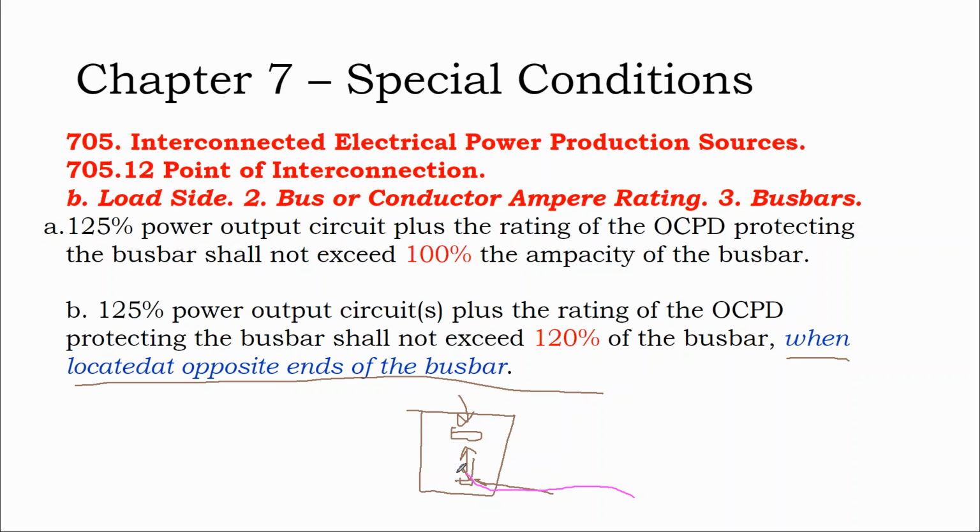So the bottom source feeds the bottom loads, and the top source feeds the top loads, and they don't mix to combine to be more than 240 amps or whatever. If you just plug in this solar inverter wherever you want it to go, then the feed from the grid and the feed from the solar could combine together and overload the bus bar.